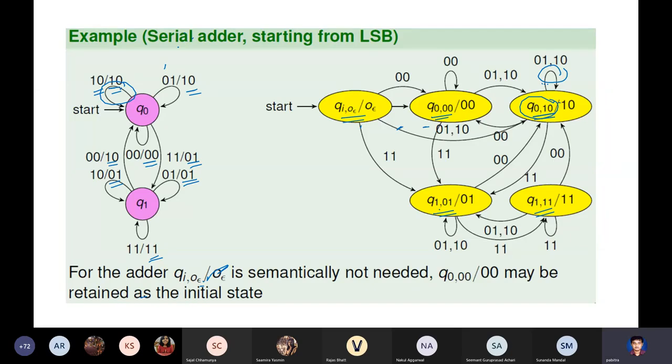Okay. What about the other one? See, another is this one. It receives an input 1 0. Yeah, so the other is one of these edges. Okay, so this way it's very easy to decide the edges. You just find out what is the destination state, what is the next state from there, and you draw an edge from the present state to that. Okay, similarly you can complete.